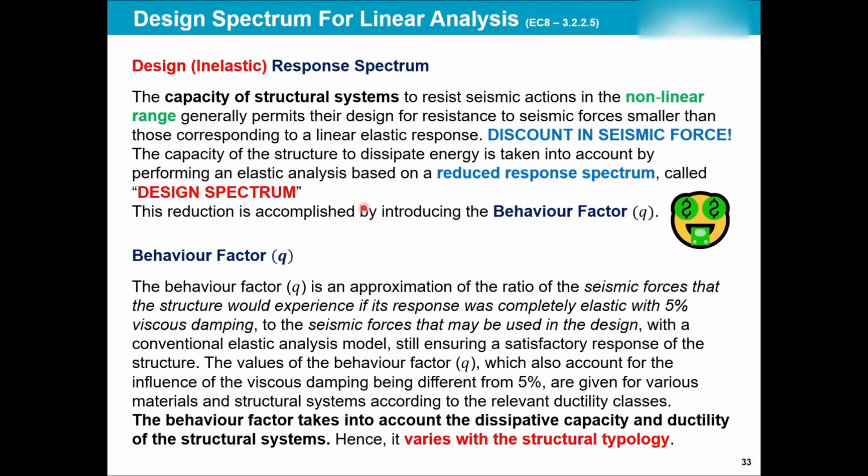Now, so far we discussed the elastic response spectrum. When it comes to the inelastic response spectrum or the design response spectrum, the code allows us and gives us a discount. As I mentioned, when you use the elastic response spectrum, your spectral acceleration, depending on the period of your structure, will be higher. Then the code will give us a discount.